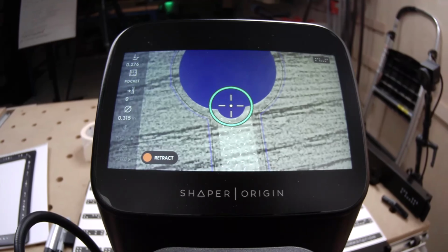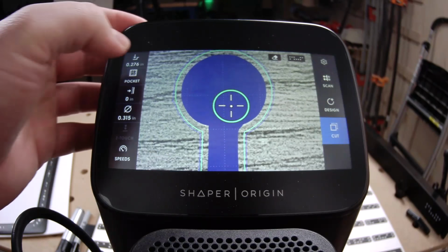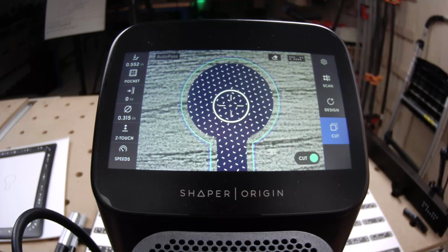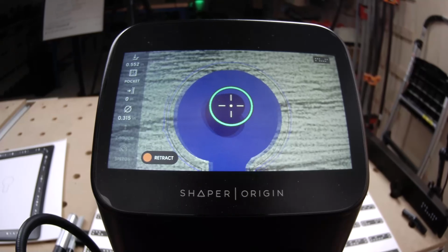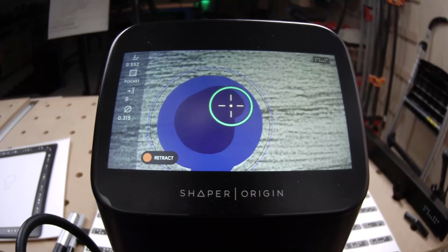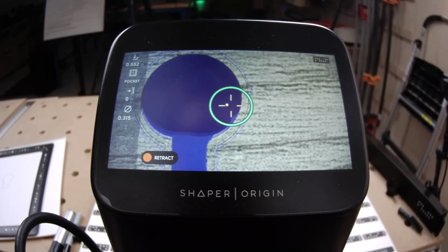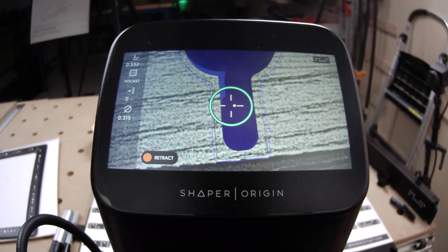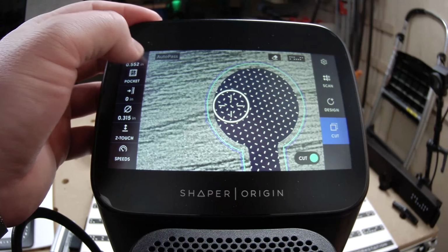Yeah, a little offset. Again, Jake is pocketing first, and in pocketing mode, Origin works like a basic plunge router that doesn't allow you to go past the extents of that pocket. He's going to take 3 pocketing passes with this 1/4-inch router bit, about 7 millimeters at a time. And then once he gets to the bottom, just like with the foam, he's going to clean up that little bit with an inside cut. Get it nice and clean.